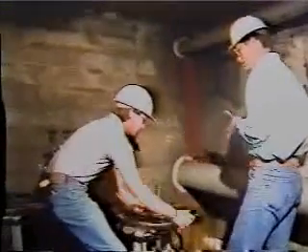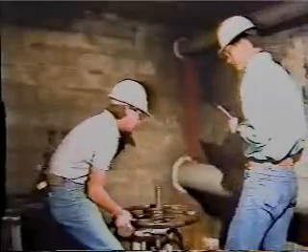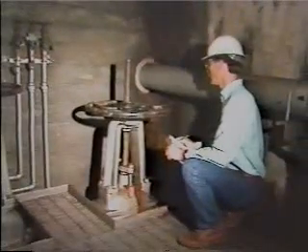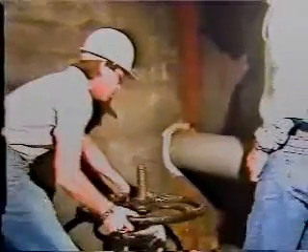First, check the operator for any problems. There may be some oil leakage around the stem, but it should be minimal. This gate valve operator is a simple manual system. The important things to check for are missing, broken, or loose parts, surface damage, and adequate lubrication. Now test the operation. Watch for any signs of rough movement or binding.